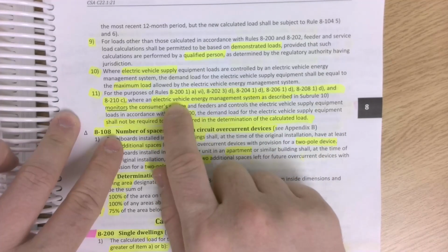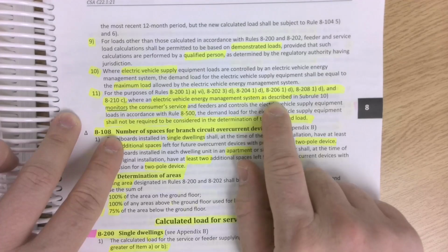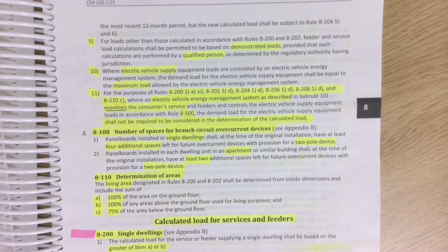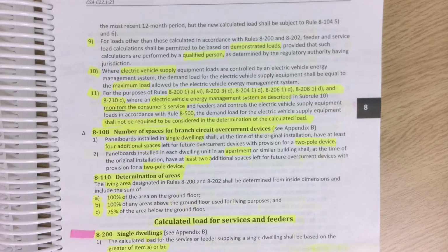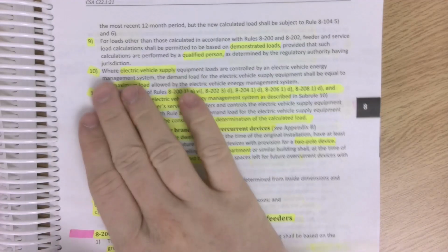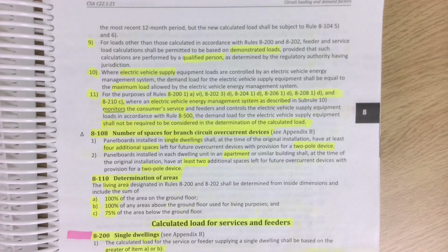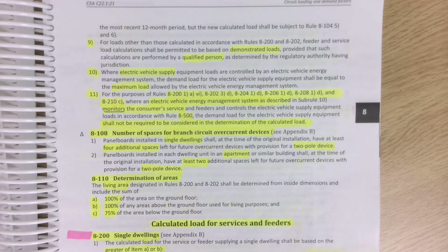So, if there's an electric vehicle energy management system, we're not going to count that EV charger towards the service. And just briefly how those energy management systems work, and it explains it in subrule 10 as well, in order to not overload the service, for example, if someone comes home from work, plugs in their electric vehicle, goes into the house and starts cooking right away, that's 2 very large loads that the service has to deal with. And so how an energy management system works is it